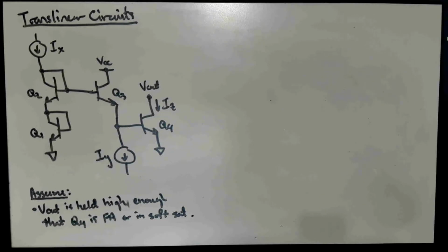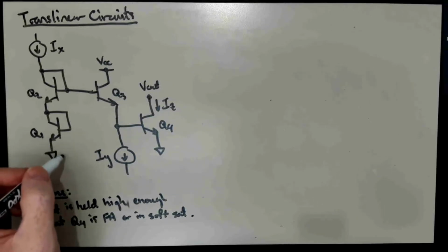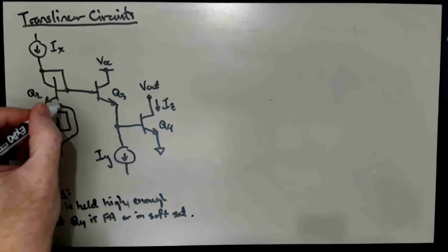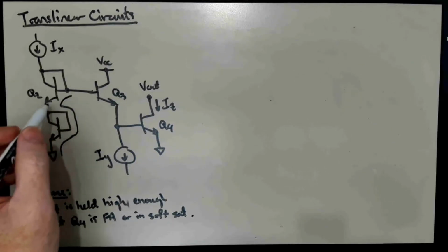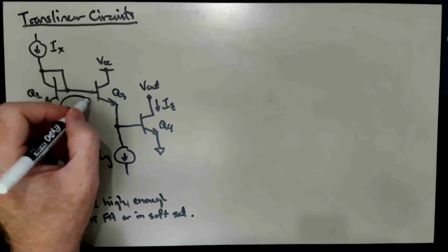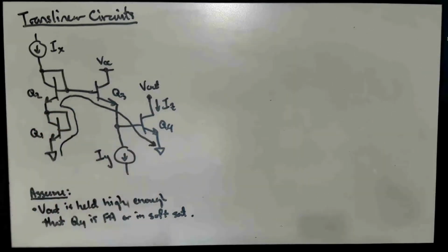And so now the question is, do we see this 4-transistor translinear loop that we analyzed last time here? Well, if we start at ground, we go up 1 base emitter drop, and then we are at another emitter through this diode connection to a second base emitter drop. It's a rise actually, emitter to base, so that matches up with what we had. And then we see Q3, base first, and we go down to the emitter, and we go down to the emitter of Q4. So we do have that same translinear loop that's embedded in the circuit.